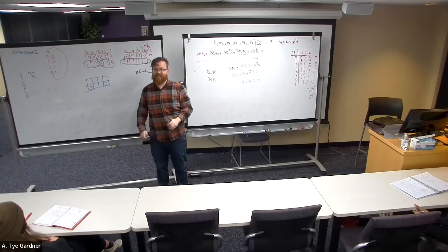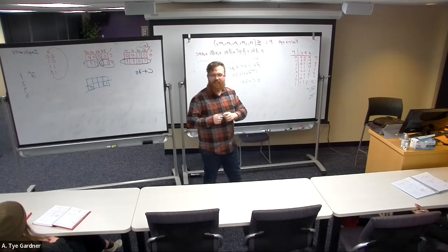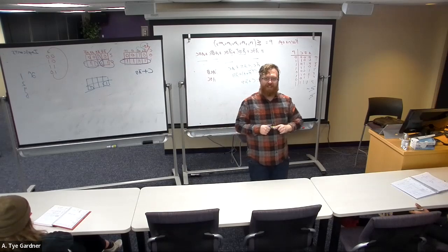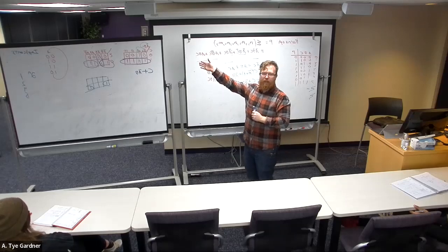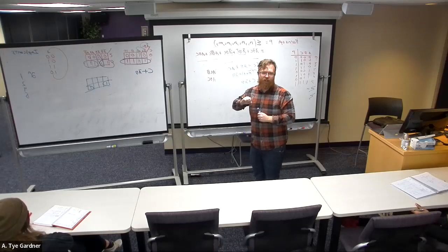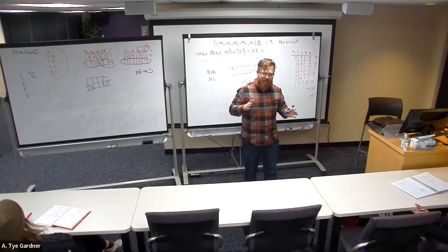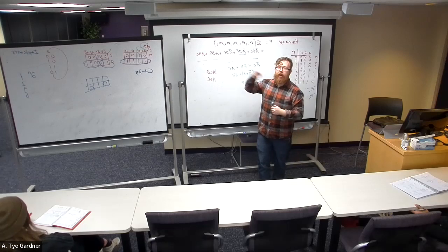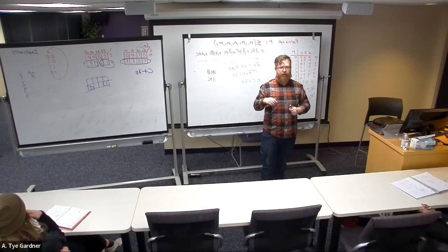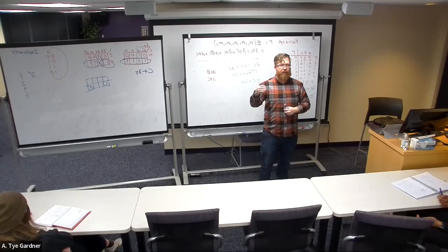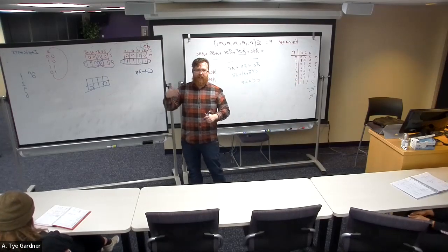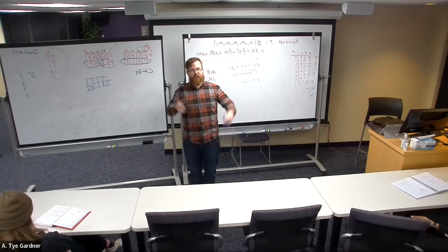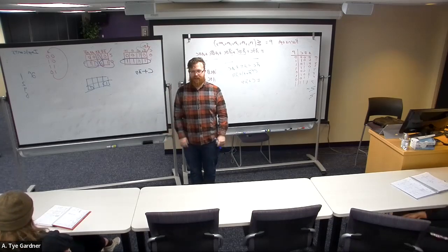Same thing. So using this will directly help you simplify your truth table. Yes. This is a wonderful way to get a minimum sum of products representation of any truth table. It's nice. It is a minimum circuit. They are not unique, right? There are multiple possible ways to solve some K-maps. And that's the difference between an essential prime implicant and a regular prime implicant. A prime implicant is just saying there's 2 different ways to complete this K-map, okay?